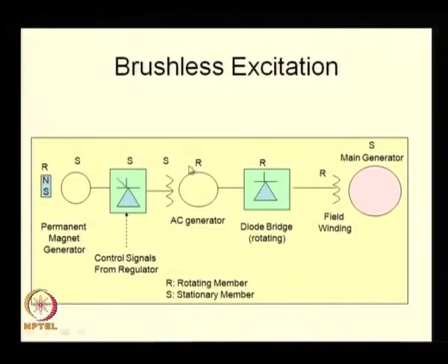So, you know how a synchronous machine behaves, but you need to model all these components here, that is the rectifier itself, then the AC generator, it is also a generator. So, you may wish to model this in detail. The amount of detail is something which is based on our engineering judgment. You also need to model the behavior of a diode bridge rectifier. These are not just algebraic relationships between the input and output, you may actually have to model some of these components at least as dynamical systems, as differential equations.